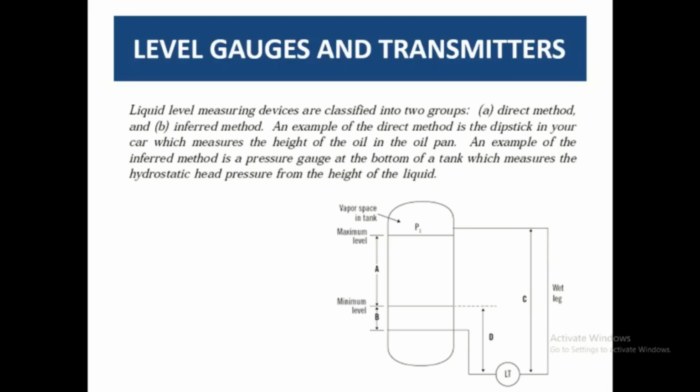On the other hand, we have studied some temperature transmitters which convert the temperature into pressure, and then that pressure value is transmitted to your control room in order to assess how much temperature is present in your process. So this is inferred measurement, because you are measuring something else but getting a different result.